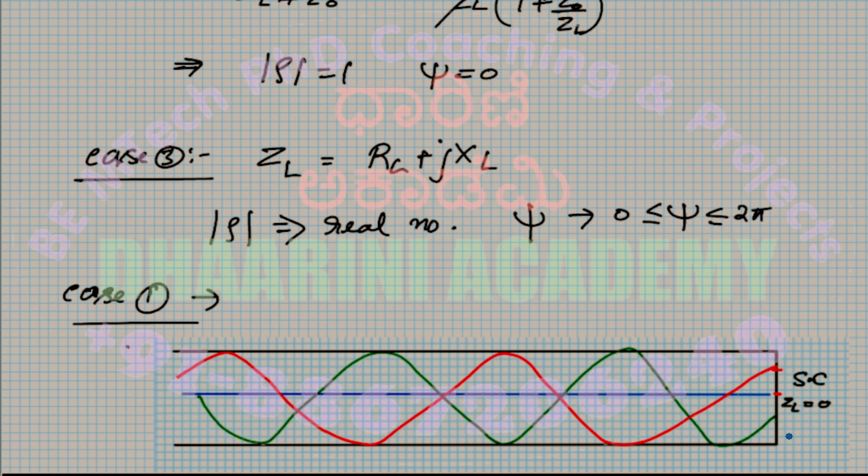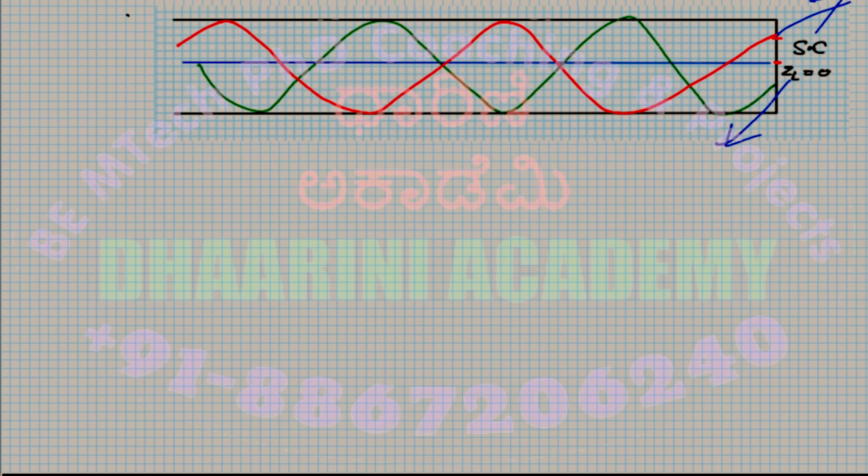So just note. Let me assume that maybe the red colored waveform is the incident. Okay, it hits the short circuited load at this point. But because of the phase being pi, everything should be reversed when it reflects back. You see, the signal was going up, it was increasing. Now you see the reflected wave is decreasing. Are you okay with that?